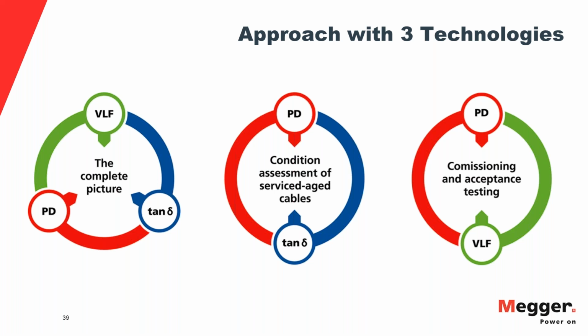So you use a radar high voltage combination, which has been in the industry, HDW patented it in 1965. Now everybody has it under a different name. We're still using arc reflection method as the name, ARM. And that is good for finding 90% of the faults in a solid dielectric easily. It's a really straightforward method to use and the industry standard.